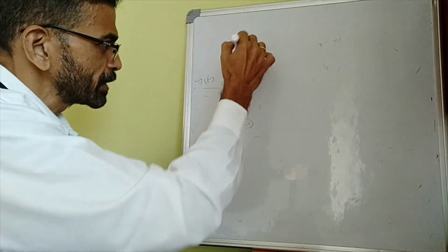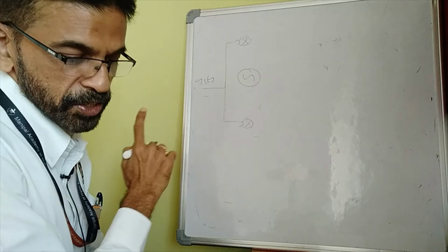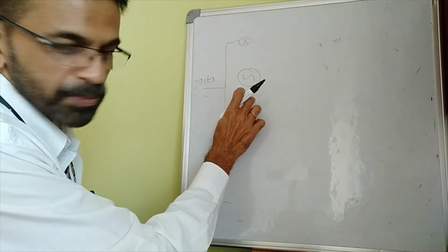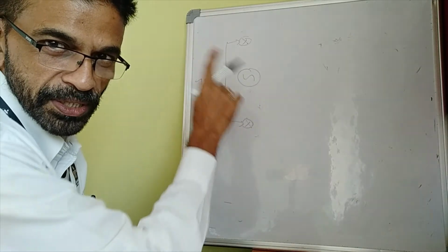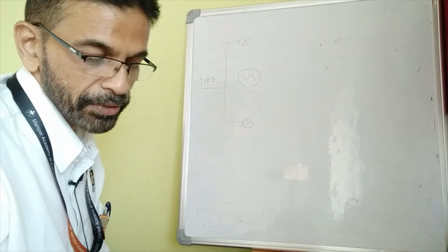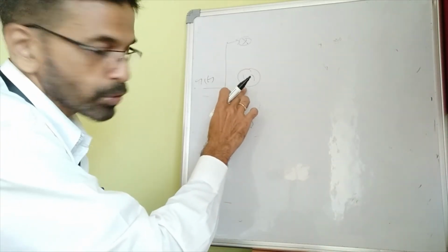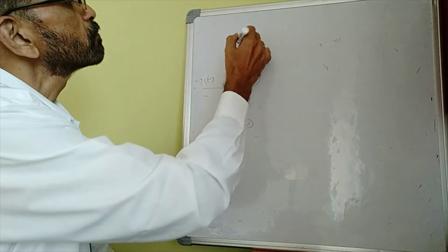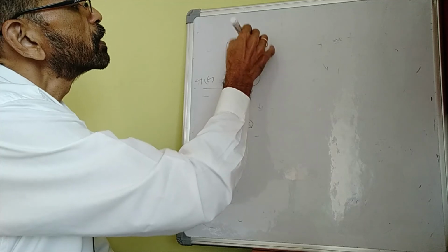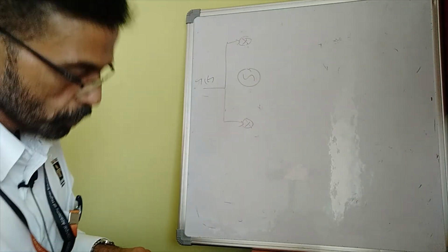Non-coherent detection we will discuss later. We have discussed earlier, in the estimation problems, how the phase can be estimated. That is not directly relevant here, but we have to understand that at the receiver you need an oscillator whose phase matches the phase of the oscillator at the transmitter.